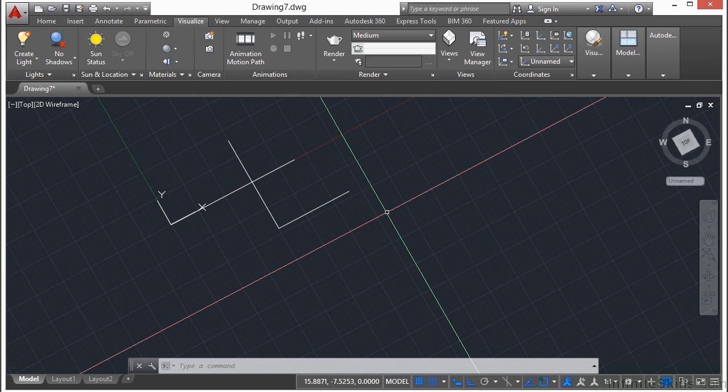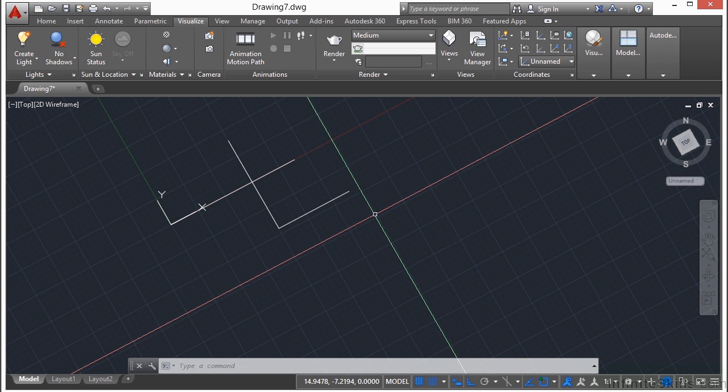Now, when you work in 3D, the UCS is key. There's a function called the Dynamic UCS feature that will automatically change your UCS to match the face of an object, allowing you to draw on that same plane as the object you selected. That's probably one of the most commonly used cases of changing your user coordinate system, when you're working in 3D. Now, that's getting a little bit heavy, of course, for this course, but it's hard enough to keep track of just 2 axes, much less 3 or 4 or 5 different coordinate systems that you might want to use. So we're going to try to keep it more simple for you in this introduction.